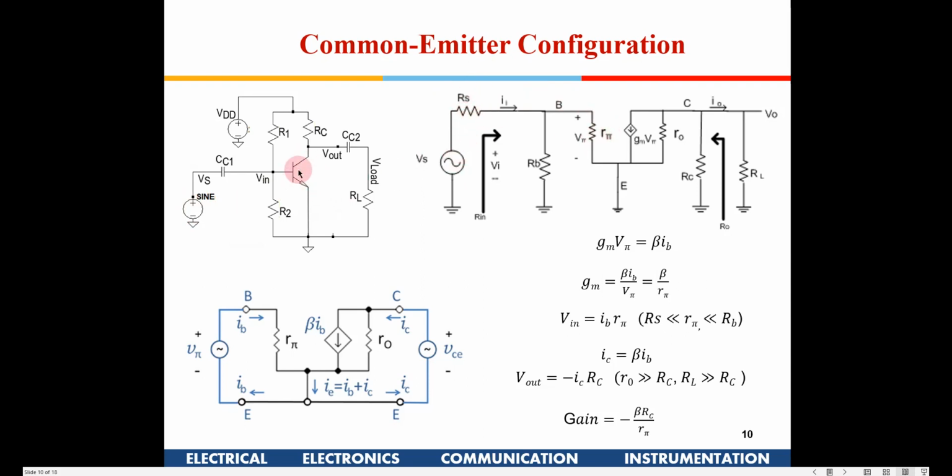And then we know the transistor in a small signal equivalent model, we replace it by R pi out here. And instead of beta IB, it is given as GM V pi. Certain textbooks follow this convention, and we'll see what the relation is between beta IB and GM V pi. IB is going to flow here, beta IB is going to flow here.